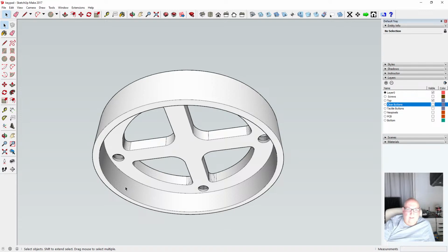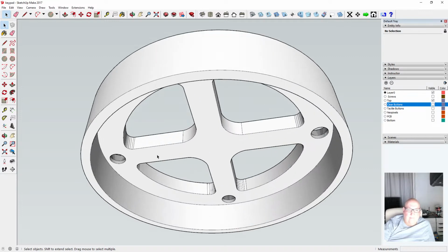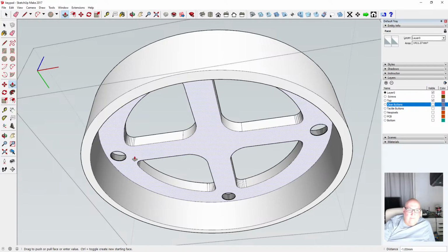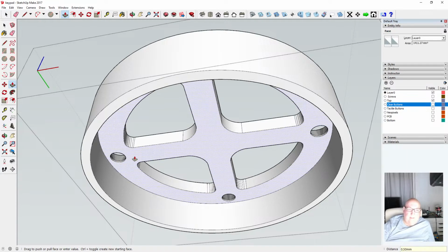This internal dimension's got to say, it's only the edge you need to drop down. But if I do that, I'll need to back this off by the same amount. Let's just do that then. Alright, let's back that off by 0.5 of a mil, because we're going to drop it further down, and that needs to stay where it is. So then we can extend this bit. No, we can't though, can we? Because we still have got only 12 mil.